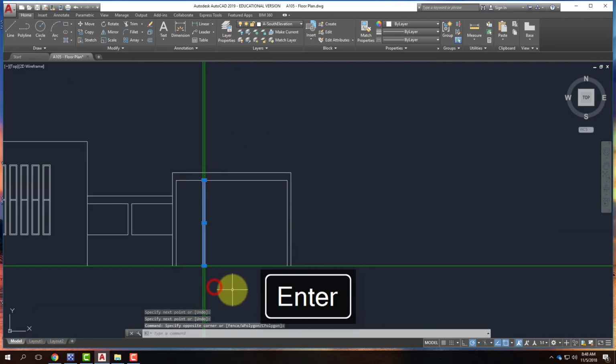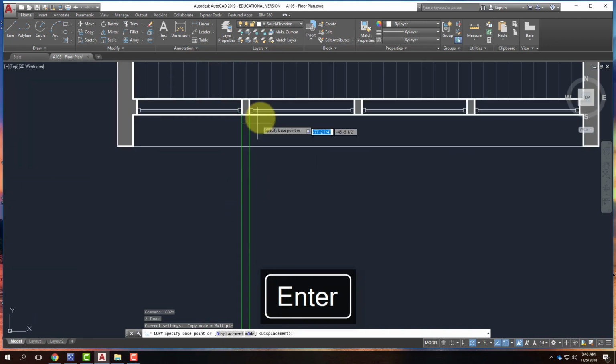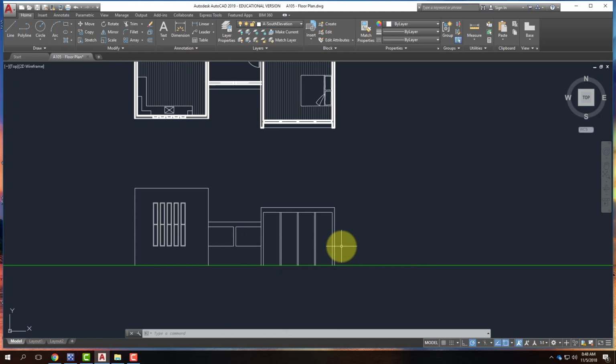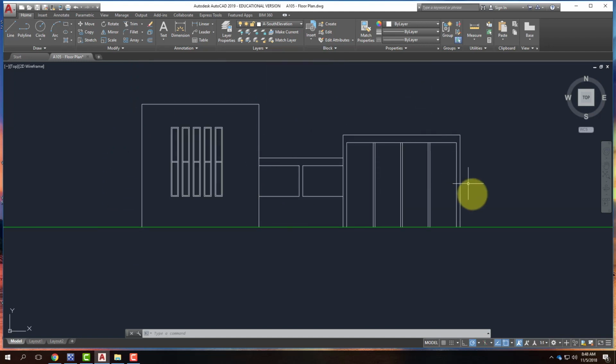And then I could take them and I could copy them where each of those divisions happen. And then I could add more detail like the cross divisions of the windows. You can use these windows as an example. You don't typically have the full height glass. You usually have some kind of a division somewhere. So putting a division in would make sense. So at this point, I've drawn essentially the basics of a building elevation. You guys are going to spend a little bit more time and really refine your elevations and understand what's happening. But we are going to draw all 4 elevations, or attempt to do that today.